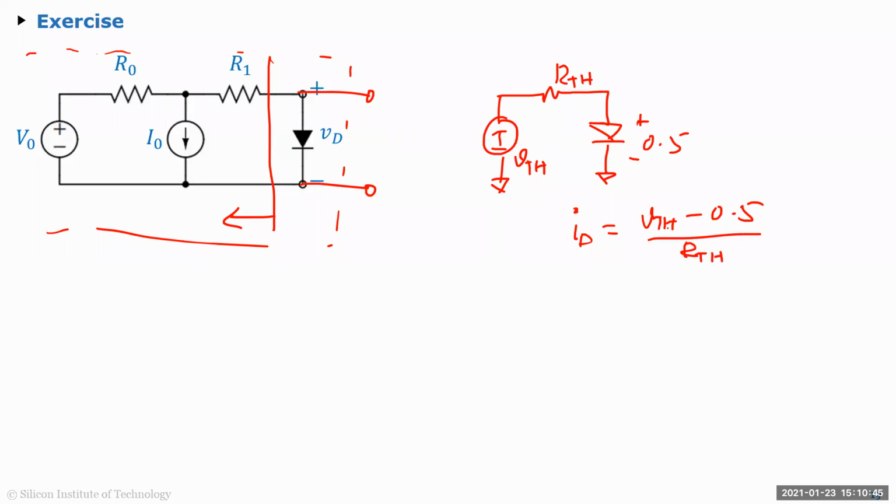By moving the circuit to the left and finding wherever you can the linear part, you get a very approximate answer, but it is actually very close. If the current is low and the diode is close to 0.5, especially if this resistance is high and this voltage is much higher than 0.5, then this equation will be very accurate, and most of the time it is.